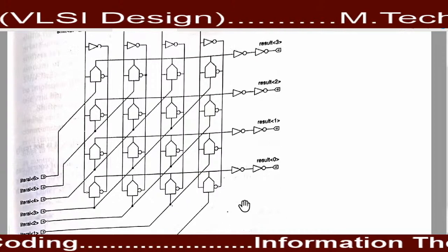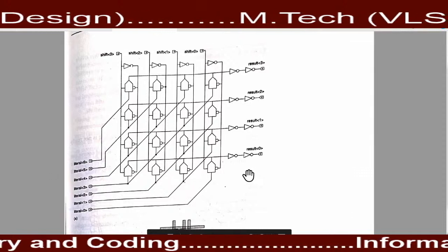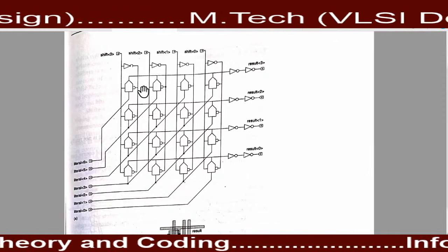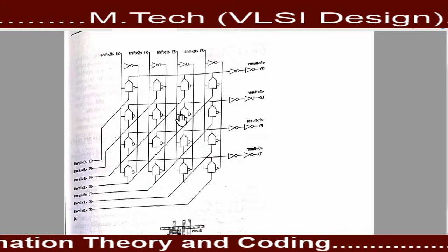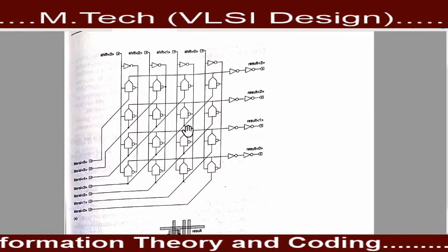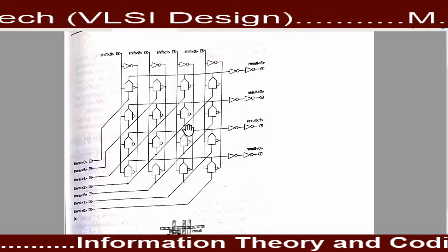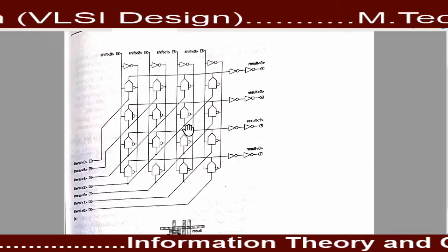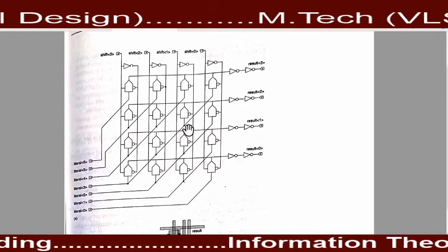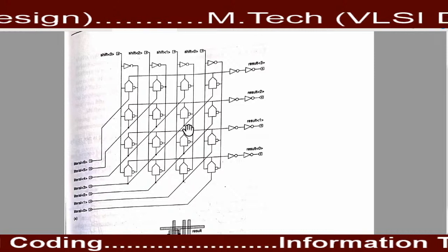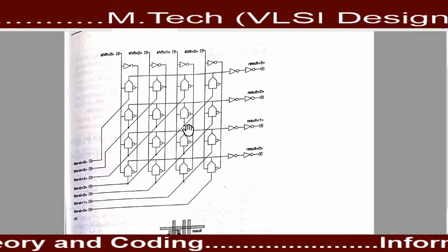In figure 8.46 the barrel shifter is represented. Here is the diagram of the barrel shifter, in which you can see various transmission gates. These transmission gates are controlled by using the gate pulse. When these transmission gates get the clock pulse and the input signals, then according to the selection line, it will provide the data to the output circuit. It will shift the data.